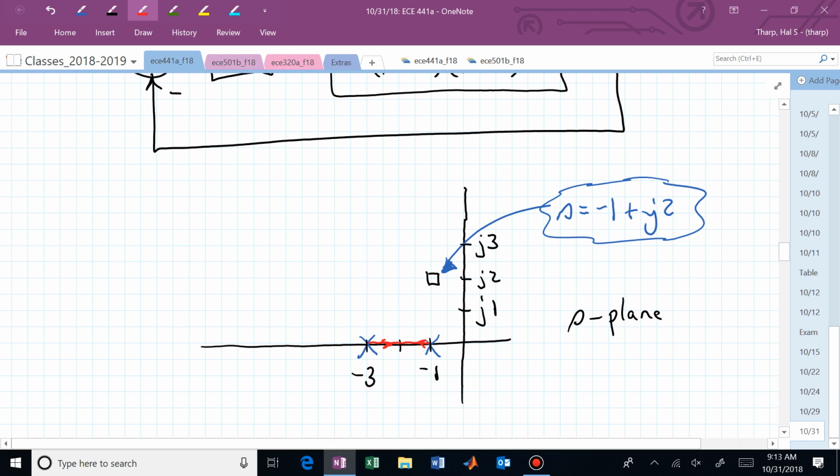So we can think about number 3 dealing with the fundamental angle. And what's our fundamental angle in this case? It's 180 divided by the pole zero excess. And our pole zero excess is 2. So our fundamental angle is 90 degrees. We have something going off at 90, and another branch, asymptote, is going at 270. So we now have asymptotes at plus and minus 90 degrees. Where is that centered? What's sigma sub a?